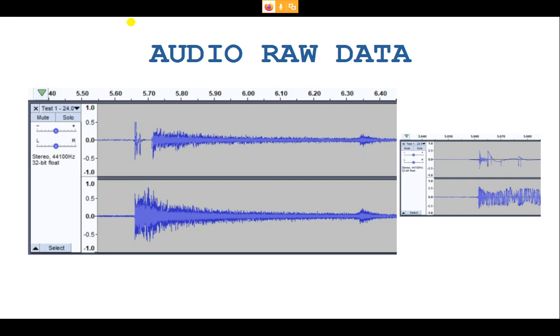We prepared our driven section, the low pressure section, with a particular separation between the microphones placed on the pipe, so we know the separation distance. Distance divided by time taken gives you the velocity.